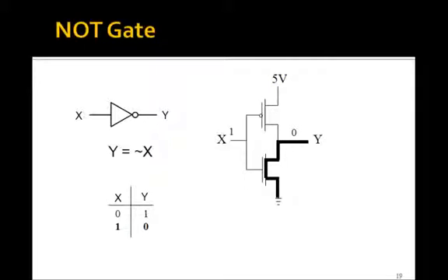So that works. Now, the reason it works is because the PMOS transistor likes to be connected to 5 volts, and this NMOS one likes to be connected to ground. That is, if you tried to put the NMOS one up here, then you wouldn't get a very good short circuit, and the same as you put the PMOS one down here. So in this case it worked.